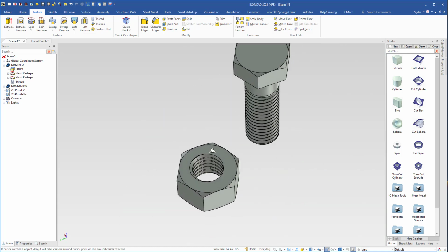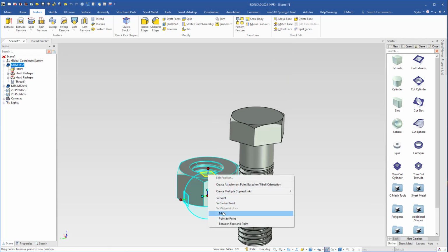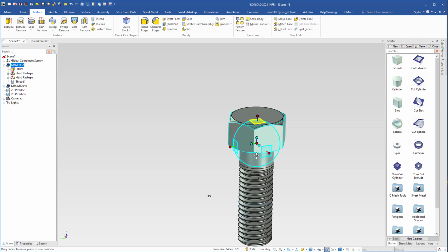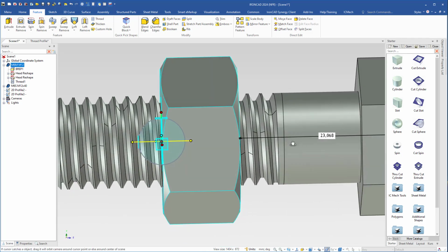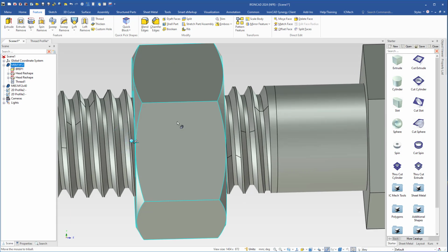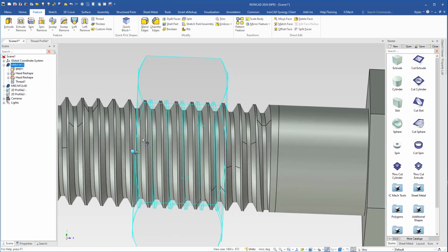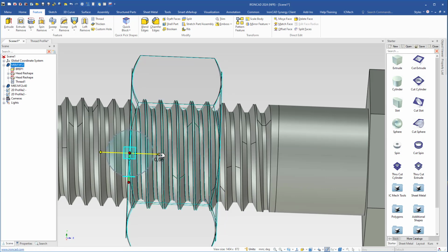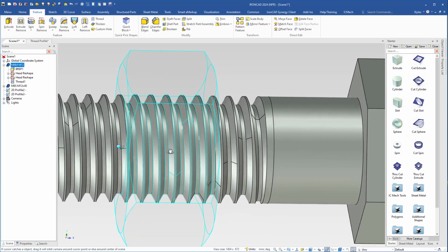So now I move this nut to the bolt, to the center point of the bolt here, drag it down a bit, like so, and then I will remove the tri-ball, right-click the selected nut, and set this transparent. Then I turn on the tri-ball again. We can move the nut so it will fit the threads on the bolt. Like so. So it will fit perfectly.